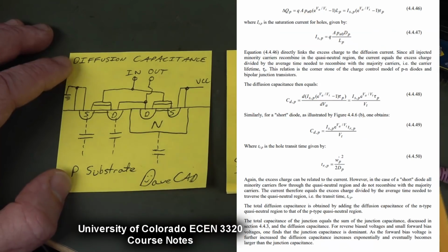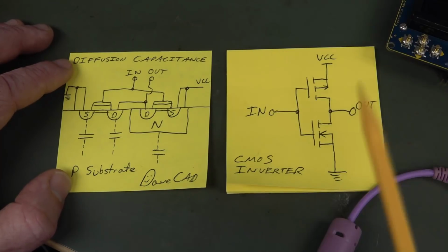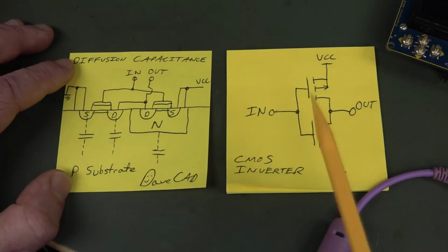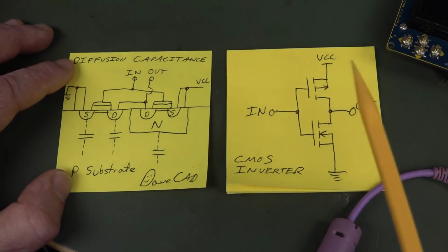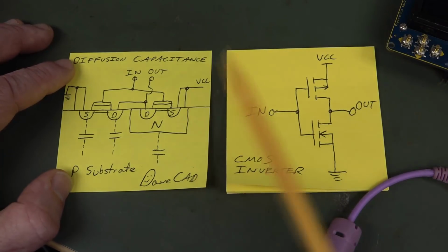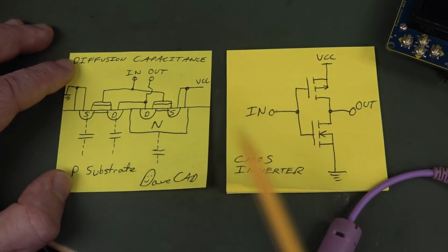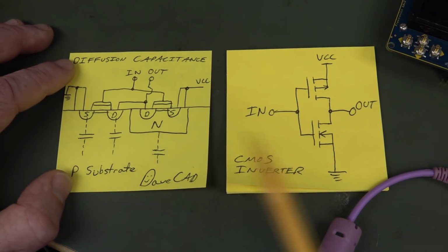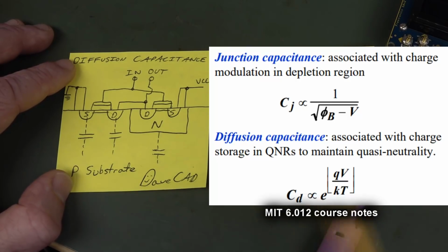But you're familiar with the normal PN junction diode, of course, which has what's called junction capacitance. That's also called transition capacitance or depletion capacitance. It goes by a couple of names, but everyone just calls it basically junction capacitance. That's where a diode has a capacitance across its PN junction, but it actually has to do with the insertion of charges and things like that acting like capacitors. And there's actually quite a complex formula, here it is, that has to do with that.